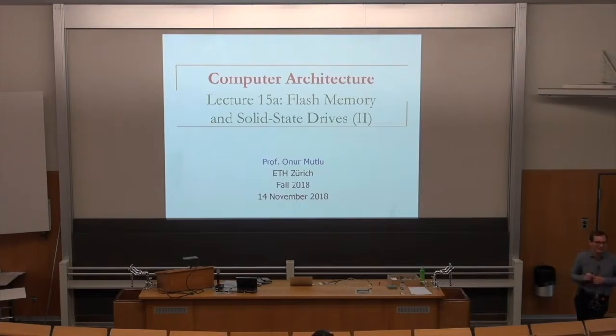Of course, this requires moving some blocks, but if you do it infrequently enough it's fine. In Flash controllers, it's very heavyweight because you have full flexibility as to where you map an address. That requires a full mapping table. But if you take an arithmetic function of the address and shift that function to point to different locations once in a while, then you do the wear leveling more efficiently.